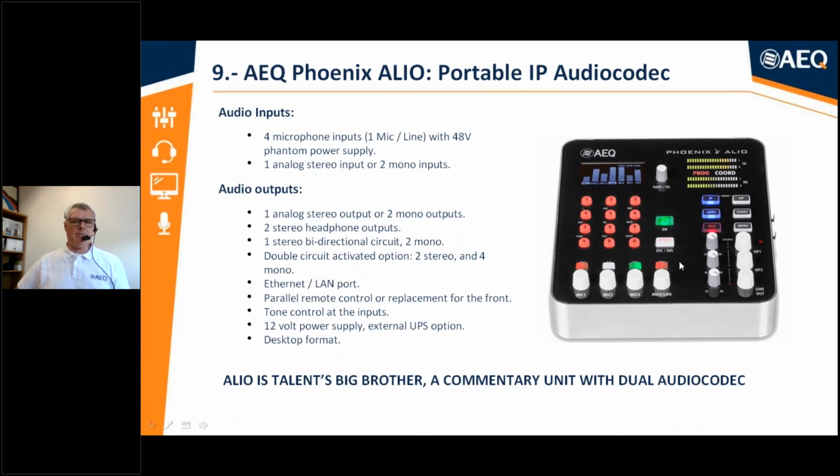As you can see, it's a very complex piece of equipment where you have 4 microphone inputs. One is a mic/line switchable one. It has phantom as well. It has the same great microphone preamps built onto it. We've got local analog stereo inputs and outputs as well that can be used as monos. So we have 1 stereo or 2 monos, both inputs and outputs. And it provides full control through the Control Phoenix. We can even do some EQ on those microphone inputs as well. It's a desktop format, very sturdy. It sits very well on the commentator desk, but it's a great mixer that is ideal for outside broadcasts.